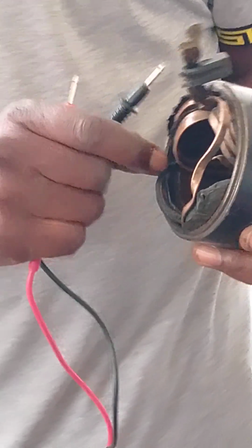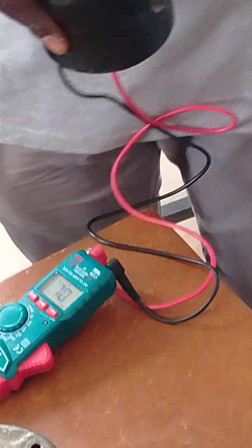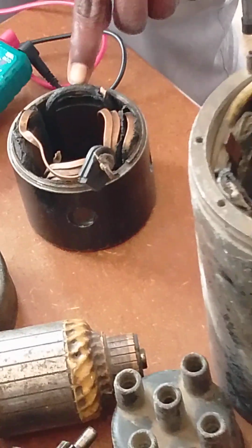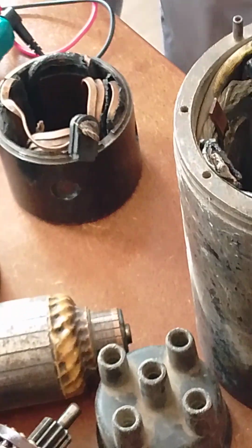My windings are insulated. What we don't want is current which flows into those windings then to ground via a shortcut path without passing through the brushes. So insulation means the tester should not show continuity. Normally we don't expect to have a continuity between the housing and the windings.